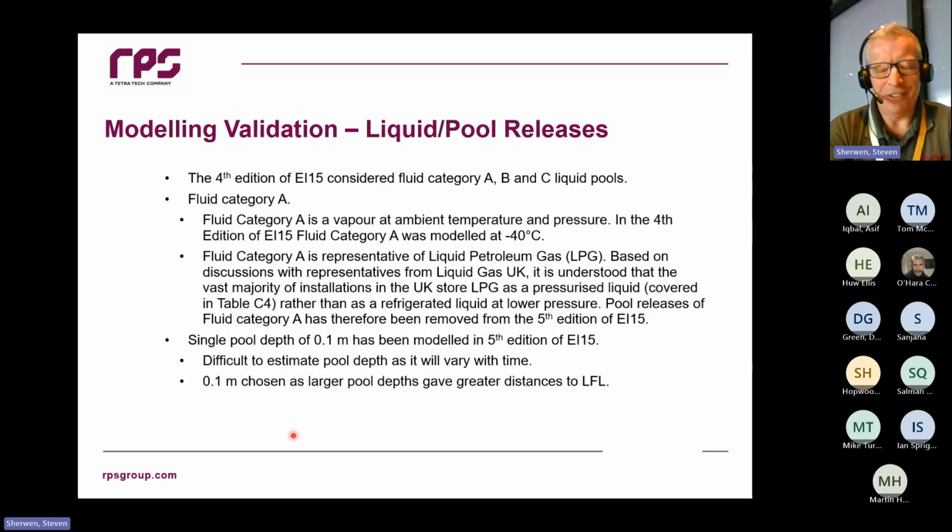The big change you'll see is that we no longer include pools of category A liquid in EI15. The reason for that is that when we looked to see how those pools had been modelled previously, they'd been modelled from refrigerated releases. So if you had a refrigerated release of -40 propane, obviously that needs to boil off before it disperses, and you do get a pool of liquid.